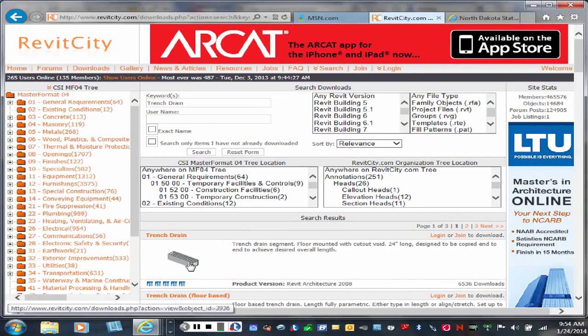This trench drain is a component. It's about 2 feet long. And these trench drains, that's the way they come. They're typically a composite shell with a metal grate on top, and they come in sections that you put together. Each section of this floor drain slopes a little more so that it ends up at the middle, or wherever the low spot is. So when you order it, you would say, okay, I need a 40-foot of trench drain with the low point in the middle, and they will automatically deliver pieces that fit together that slope toward the middle.